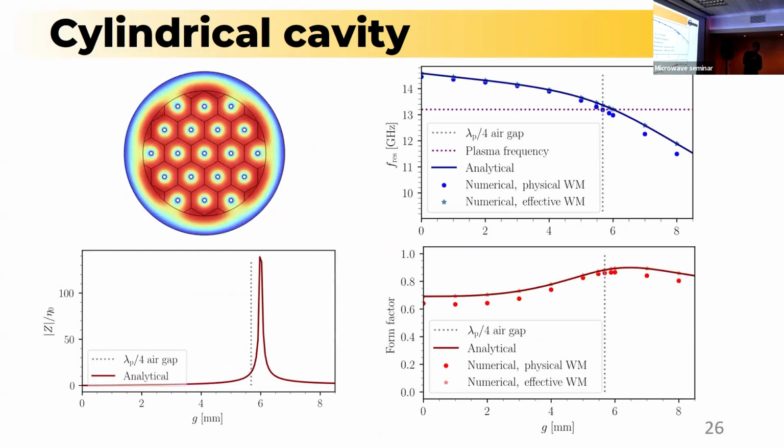We can see this behavior for the wave impedance. We have the same idea that at 0 it is a perfect electric conductor, and there is a value close to λ/4 in which we are going to have the perfect magnetic conductor boundary condition in the wire media. In comparison, considering the resonant frequency, we are going to also have a similar behavior.